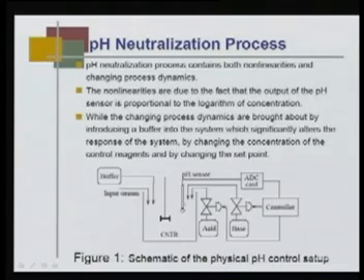There are two ways you can control the pH, by either adding acid or adding base. Sometimes people have only one agent to be added, either acid or base, but here we have multiple inputs. You can select acid or sometimes base. So there are 2 inputs here, and finally the output is only a single output, the pH of the liquid contained in this reactor.